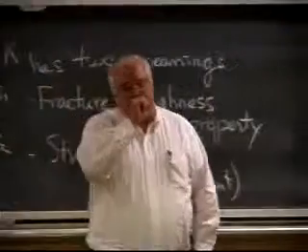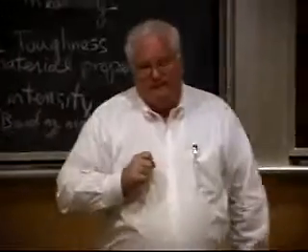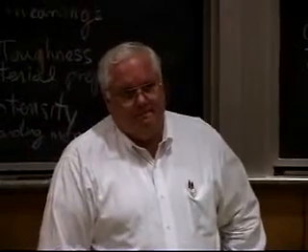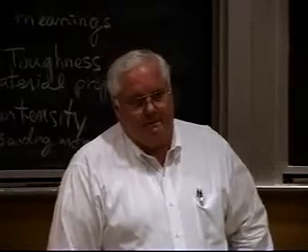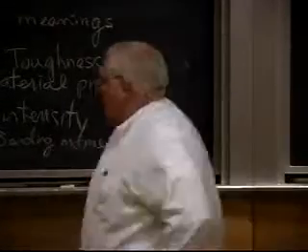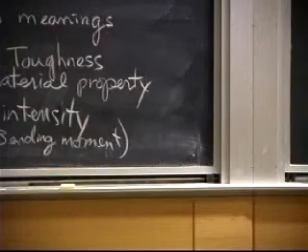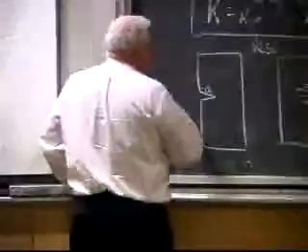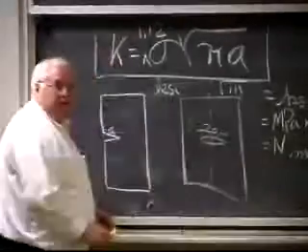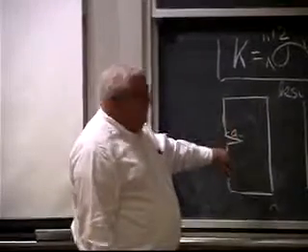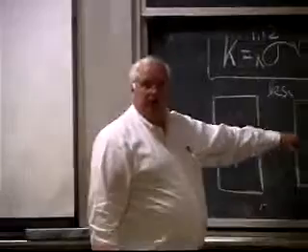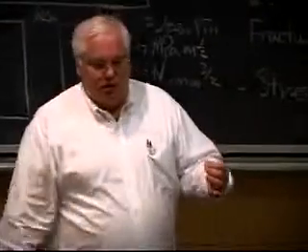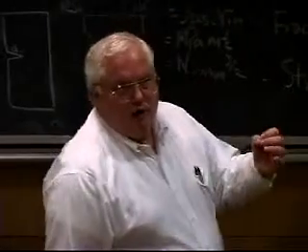Other questions? In this case, are you looking for a single flaw that's that size, or normally, don't you take like an area and you count the number of defects? I know in a lot of welding processes you do that. Right. So like a percentage or something to that effect. Well, surface flaws, first of all, are more harmful in general than internal flaws. Why? Because often the thing is loaded in bending, and the surface stresses are higher than the internal stresses, which are closer to the neutral axis, right? So internal flaws are harder to detect, but they're not quite as bad.